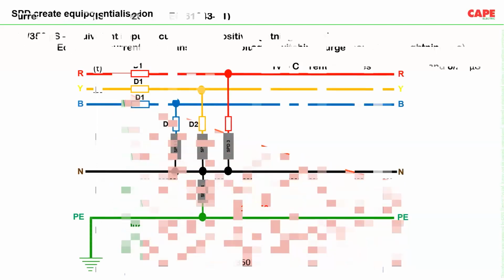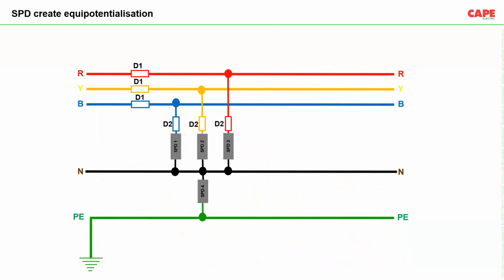Now we are going to see how an SPD is connected in an electrical circuit and how it operates. So this is a typical 3+1 connection shown for a 3-phase 4-wire system or 3-phase 5-wire system, as we may say. So we have a 4-pole SPD, SPD 1, 2 and 3, which is connected between the 3 lines and neutral. And then we have SPD 4, which is connected between neutral and earth. This is called a 3+1 connection. Similarly, there is one more connection which is called a 4+0 connection, in which all 3 lines and neutral are directly connected to earth. Just for the sake of understanding, for catching up, because we already discussed this in the last webinar, we'll just discuss this thing.